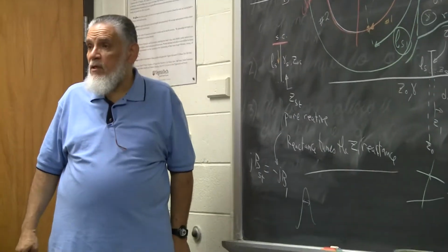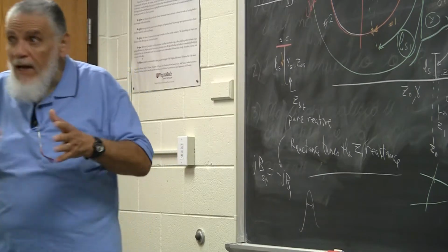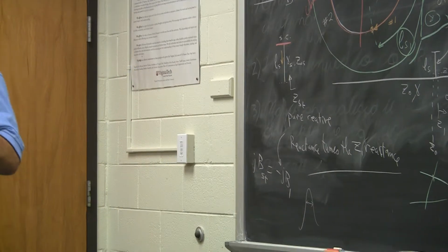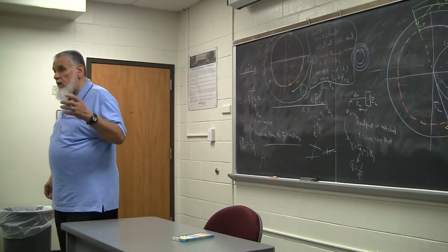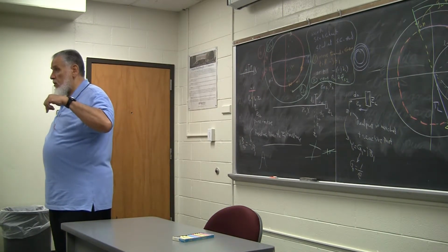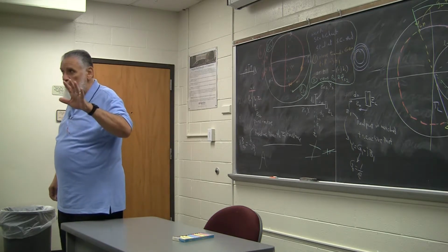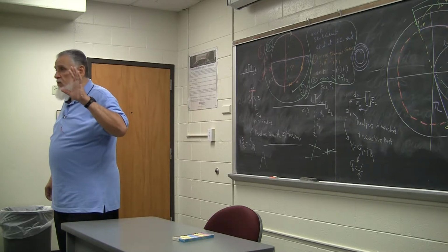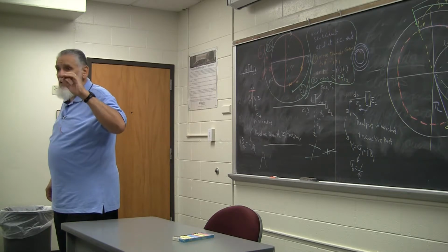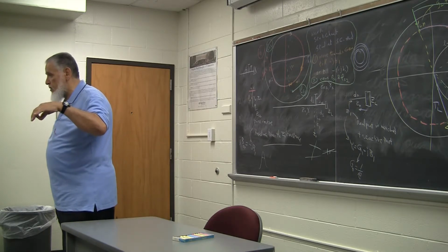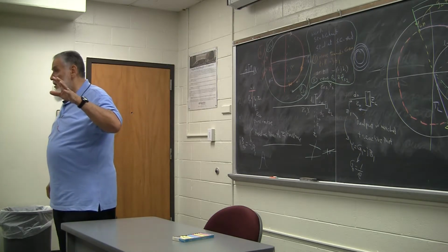Supposedly, in all these circuits here, transmission line wise, they are supposed to be flat with frequency. In other words, the bandwidth is very large. As it turned out, what limits the bandwidth in transmission line circuits, not the resonance ones, the regular ones, is not the losses as much as it is the excitation of higher order harmonics, higher order modes.